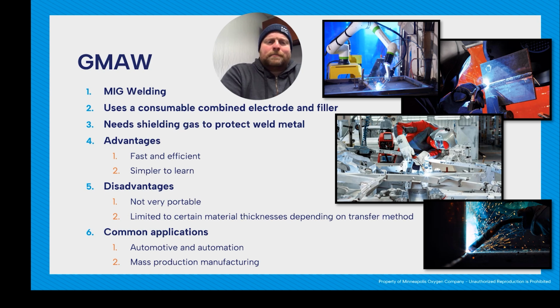All right, GMAW, also known as MIG, uses a consumable combined electrode and filler. So when we talk about something like this, and like with SMAW, your electrode is what conducts the electricity into where the weld is happening, and then the filler is what gets melted with your base material to form your joint. So in stick, your electrode and filler were the same thing. GMAW, electrode and filler are the same thing. You need shielding gas to protect your weld metal.